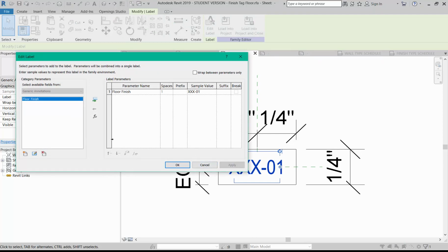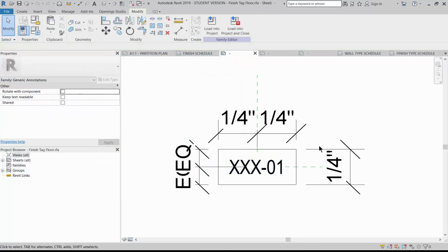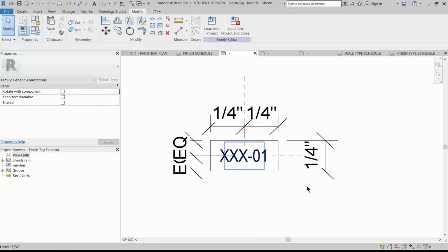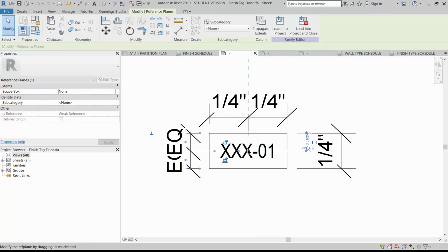And this one's actually set up so it could even be scheduled, but you just have a single text parameter. Just make sure everything is text like in a keynote, and it's 1/2 inch wide and 1/4 inch high. One thing to make sure with all of your symbols is that they are set up to approximately the same size, and also because we use leaders with these, you want to make sure that those guidelines that you started off with, same as in a keynote, are centered on whatever symbol you're using.